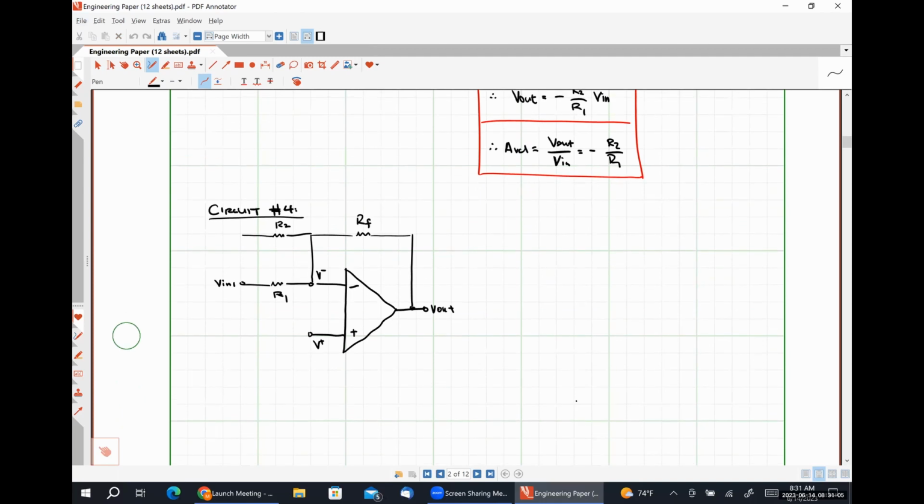So we're going to have an input signal VN1 applied at the left leg of resistor R1, and we're going to have an input signal of VN2 applied at the left leg of resistor R2. And we could add more resistors and more inputs if we needed to process more inputs. I'm going to ground my non-inverting input terminal. And now we're in a place where we can analyze things. Right? So by inspection, the voltage present at our non-inverting input terminal is 0 volts.